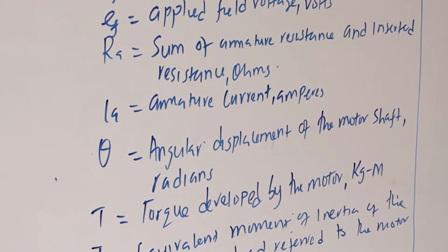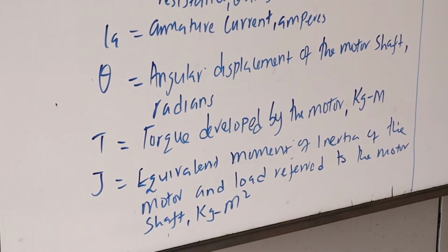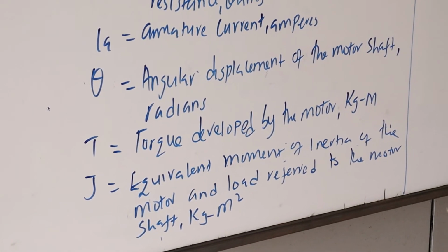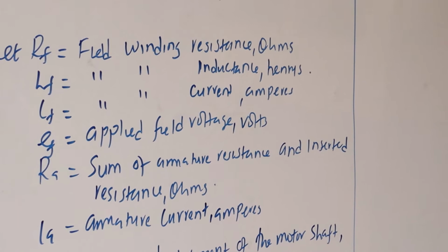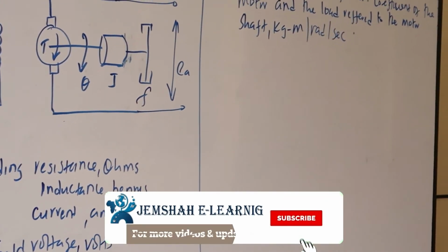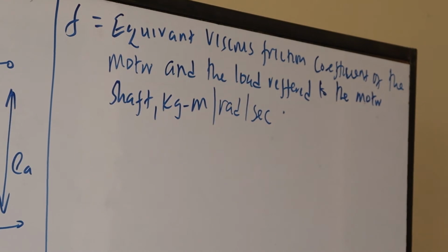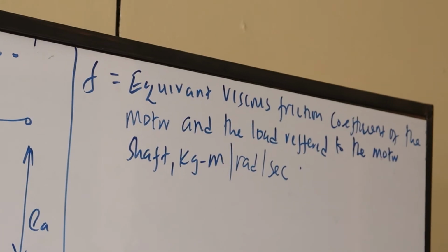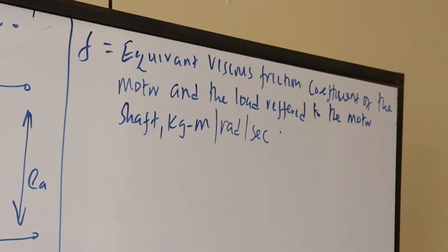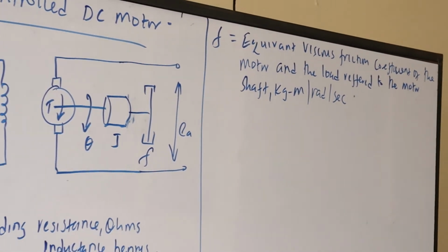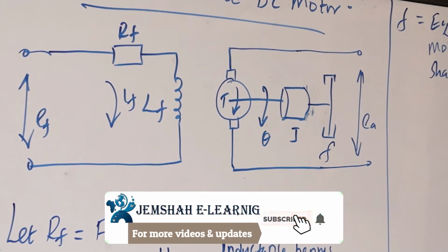So in this particular system, the field current IF is actually the control input, and the armature current IA is always maintained constant. This may be accomplished by applying a constant voltage source to the armature and inserting a very large resistance in series with the armature. If the voltage drop in this resistance is large compared with the maximum back EMF generated by the rotation of the armature, then the effect of the back EMF is made very small, thus keeping the armature current constant.